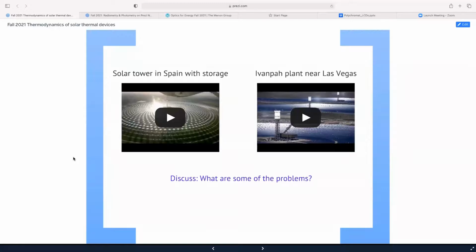In other words, what you're saying is if you concentrate it right onto PV and use electricity, that might be better. Now, the reason they don't do it, by the way, is because unfortunately, there are two problems. One is if you concentrate this much on PV, the efficiency of silicon drops dramatically. There are some materials which might work, like gallium arsenide and III-Vs and so on. We'll talk about that later on. But they tend to be very expensive, so really hard to scale up. And the second problem is that to scale up, the cost becomes very high. That's a good point. Anything else?